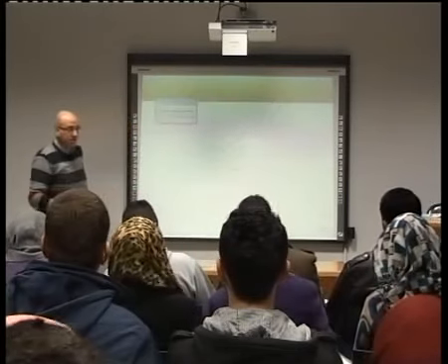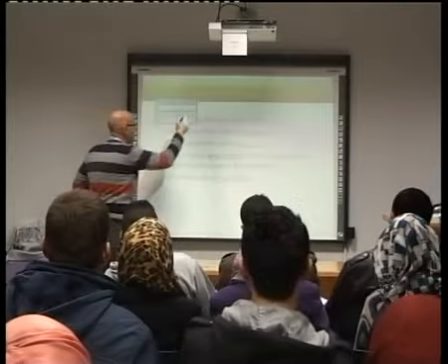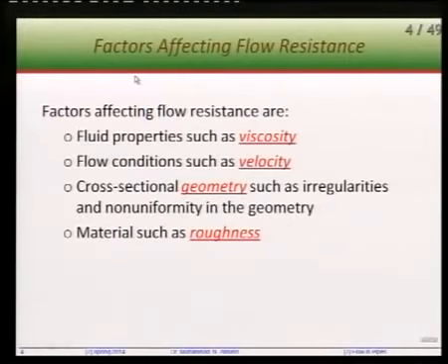Now, this head loss, we said also in the first lecture, depends on many characteristics, depends on the viscosity. Quickly, what would be the impact of viscosity on the head loss? As viscosity increases, the head loss increases. Why? Because it will be difficult to move, to drive the fluid. Yeah, so it's easier to pump water than to pump honey, oil, mercury, whatever.